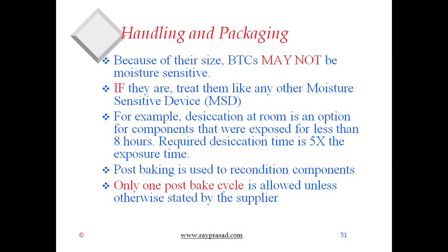So if you have to bake a package, what that basically means is that you have failed in your process of handling the moisture sensitive package. So each baking is a signal that the handling procedure has failed, because ideally we do not want to bake, and we shouldn't take that lightly, especially since we are using those no-clean fluxes and this higher temperature reflow soldering, and you're going to create more defects if you have to bake it.